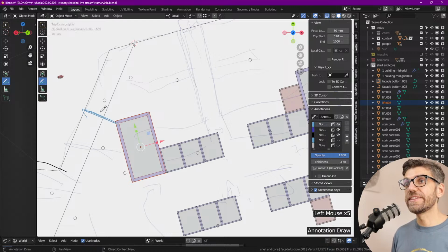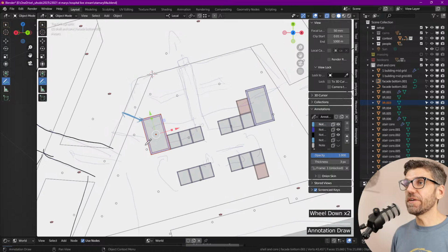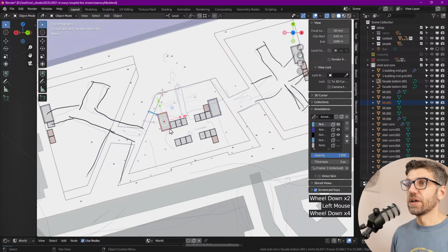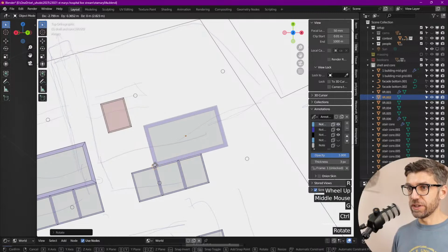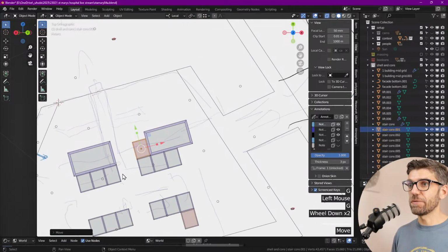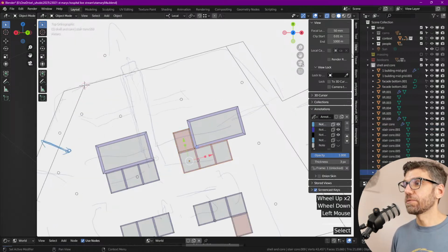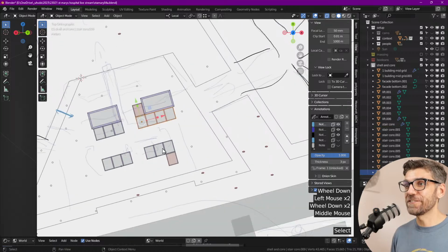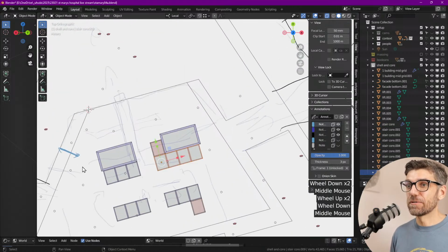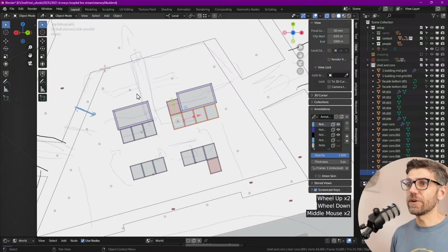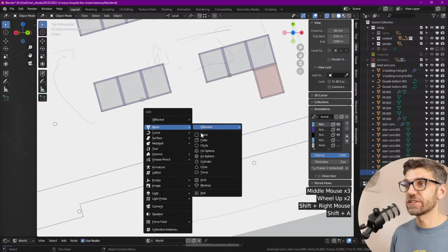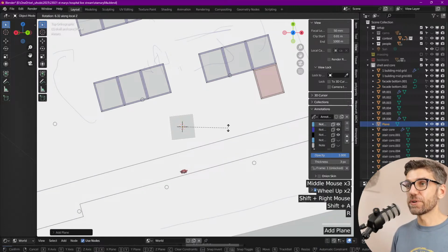Like we want that depth from the edge of this core and here to be usable. And that's quite tricky. Now there are other ways to think about the cores as well. It will stick out a little bit more on this side, but that could actually prove useful because then, what can we do here? We can put another lift. In case we don't have enough lifts, we can always put another one, right? So maybe that gives us a little bit more, and it's occupying that base area that's not very useful. Now I want to check this distance here because it's very important to have the generous area.